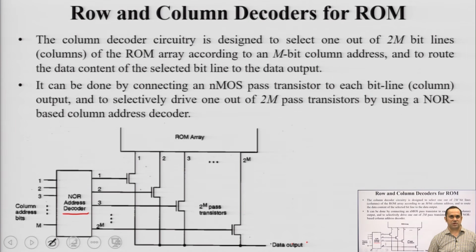So, it does two things, it identifies the location in the column, and it also helps you to do the read operation. For the write, you can use a NOR based and a NAND based circuit for writing the data. In a NOR based circuit, you access by making that particular row 1, and for columns you just go by the absence or presence of the device there. That is how you do the writing part.